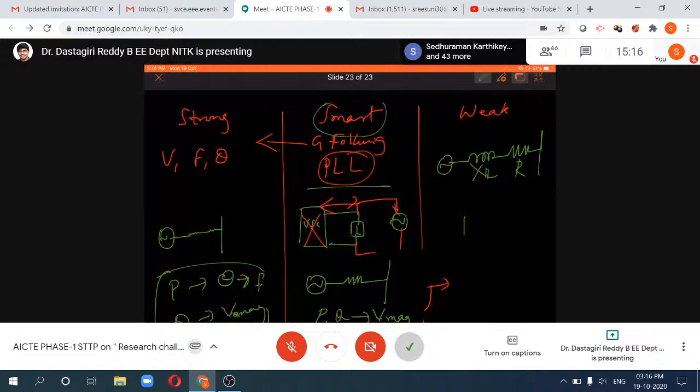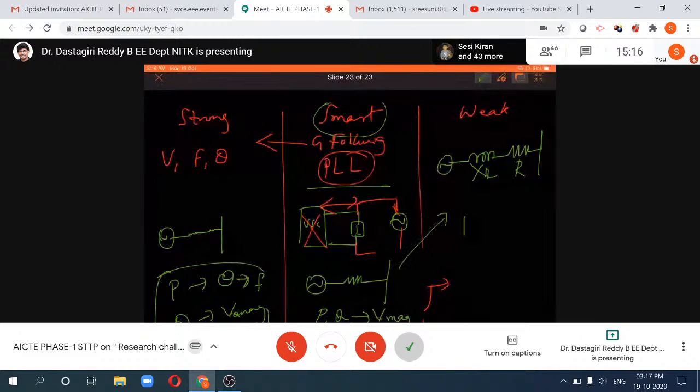For example, if you are dealing with this guy, and there is a change in power, if you keep on varying frequency, it may not work out. You have to see what the actual relation is, and then tune accordingly which factor will be affecting the power and which will be affecting reactive power. In that way, you decide your control strategy.